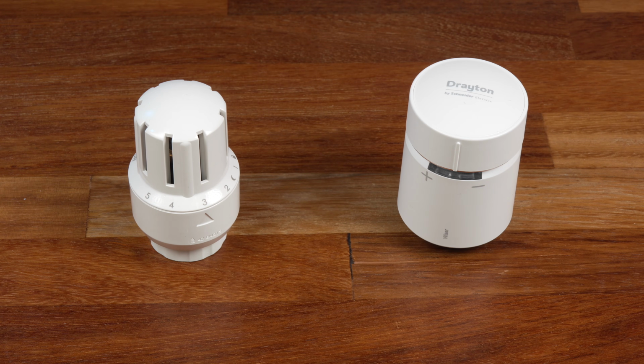Another example where smart TRVs could be very useful is in a house where you don't have a downstairs hallway and your thermostat is in the living room. You could very easily have a situation where everyone's in the living room and therefore the room gets quite hot just from the people that are in there. This could keep your main thermostat switched off while all the other rooms upstairs in the house are starting to get too cold. Adding in a smart radiator valve in maybe 1 or 2 of these upstairs rooms would allow those rooms to trigger the boiler even if the main thermostat in the living room isn't requiring heat.